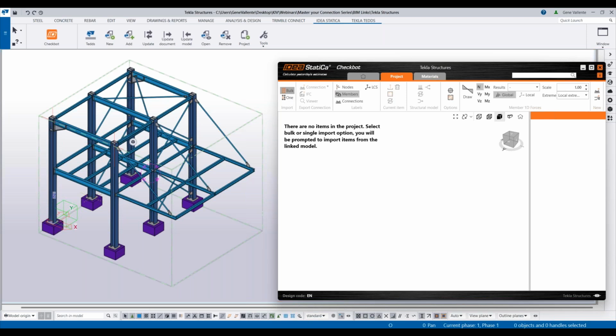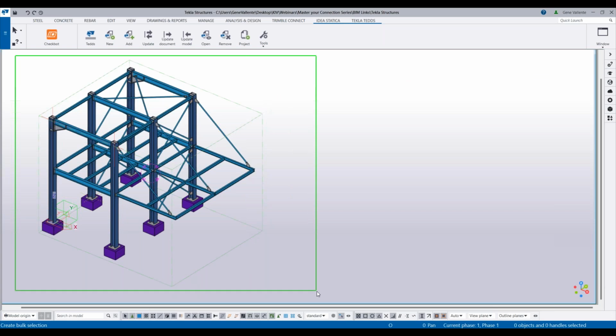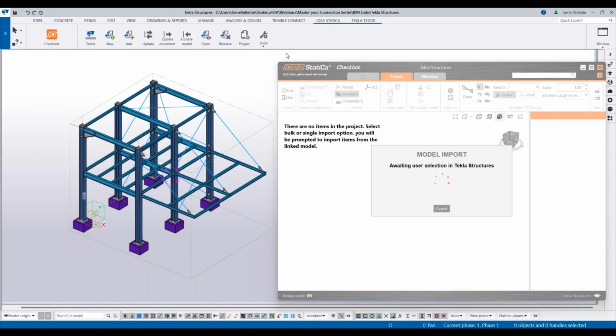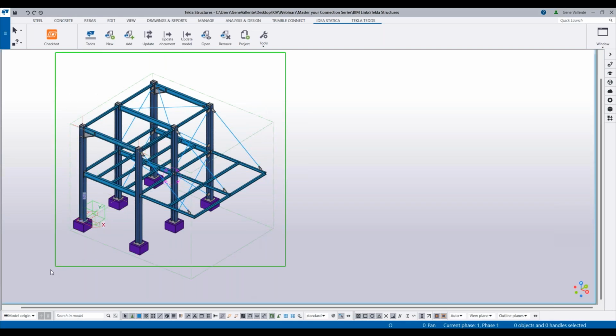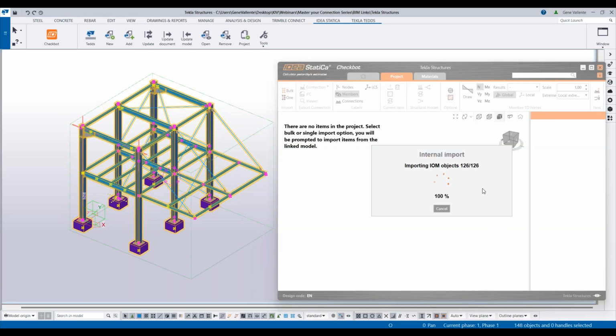to select in Tekla Structures. So all I do is go right over here, and then when I click on there, I hit my space bar. Once I hit my space bar, this one will appear, and then I go back again and hit the space bar. You will notice that there are nodes already captured here. When the nodes are already captured and I hit the space bar, it will start the import.